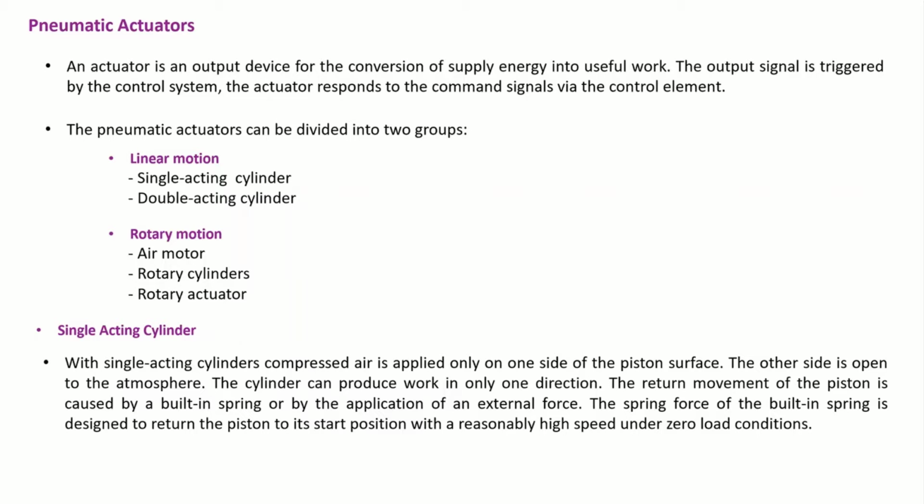The return motion of the piston is caused by the built-in spring inside the single acting cylinder, which applies the force needed for retraction. The spring force of the built-in spring is designed in general to return the piston to its start position, which we generally call the fully retracted position.